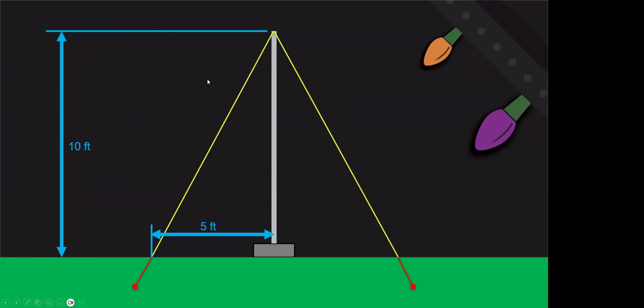But it's all based on angles. So let's say you have a 10-foot tall mega tree, your guy wires are 5 feet out. Ideally, you want them as close to horizontal as you can get. Realistically, nobody's going to put them out 30 or 40 feet because you can't get that far. So here I just assumed it was half the height. That results in a guy wire length, if I were going right to the top, of 11.18 feet. For those of you that remember your geometry or trigonometry, that would result in an angle of 26.56 degrees.